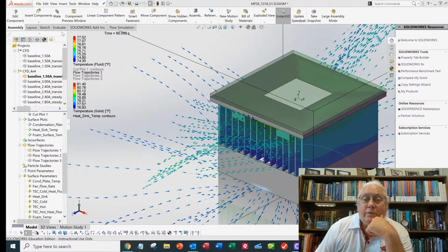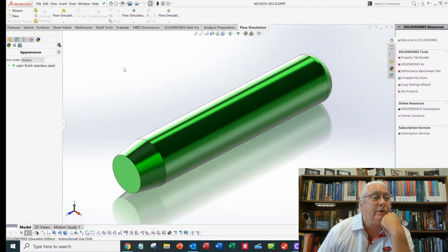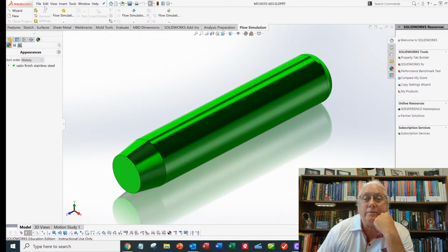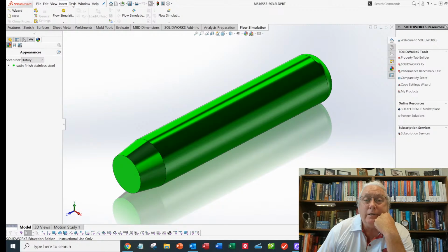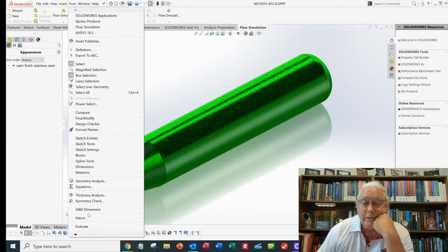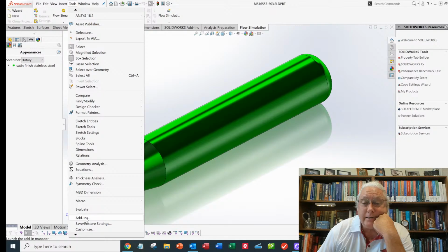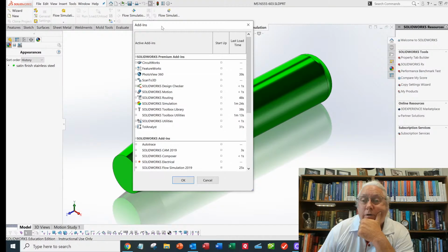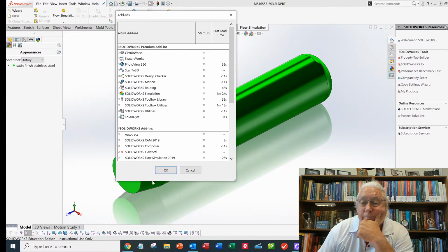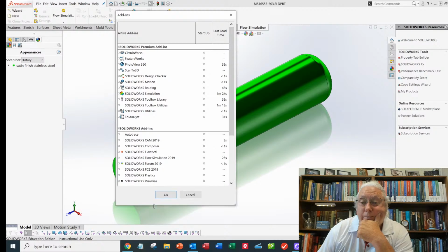So the first thing you'll do is need to get SOLIDWORKS education version. If you're a student, you can get that through the classwork. Okay, yeah, stress analysis. So that's right up my alley here. So let's see what we got here. You've got to go SOLIDWORKS, Tools, and we got to look at these add-ins and see what kind of modules we have available. And so you'll want to do the same thing on your computer. So we've got SOLIDWORKS simulation. So let's turn that on.